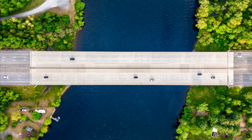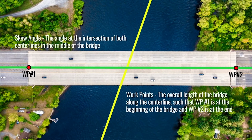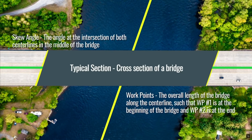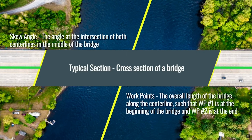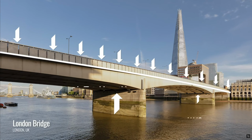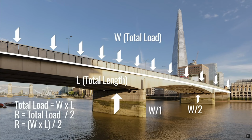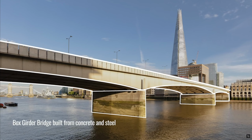How do you decide what kind of bridge to build? Right, so there's a couple of things we look at when we want to design a bridge. So you look at skew angle, you're going to look at stationing or work points. You're also going to look at what we call a typical section, which is what is it going to look like once we slice this bridge in half? What do we want that typical section to look like? And then from there, once we get that, it's a matter of calculating the loads that the various lengths of girders or various length of materials that are necessary. We're going to also look at the material that we want to use to then be able to produce that typical section that we desire.